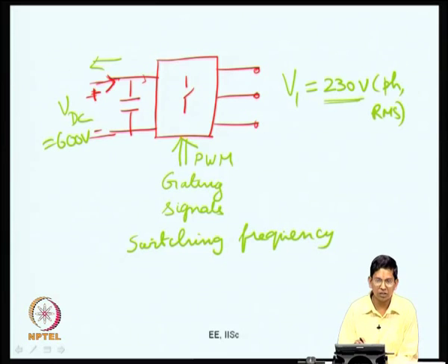And during the switching transitions, what happens? Both the voltage and current are significant. So, there is certain amount of switching energy lost. Ideally, in a switch there is no power loss at all, because in the on state the voltage is 0, and in the off state the current is 0. So, the product VI is always 0.